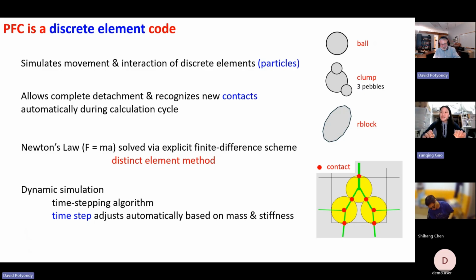And we'll talk about this more. But the key element is that the time step has to be small, because if it's too big, that integration approach will not work, and the system will not follow the right path. It'll explode. Okay. So there's a critical time step, meaning that to make this work, the time step has to be the critical value or smaller.